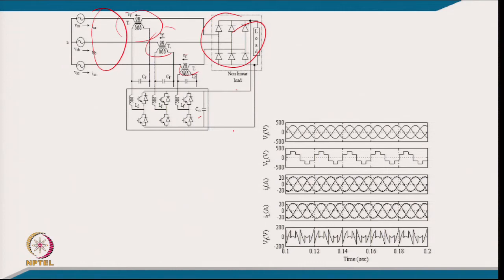So, in that case, after making the complete design and model of it with the data given in the problem, the waveforms are simulated and these are the simulated waveforms. The 3-phase supply voltage is balanced sinusoidal, and because of the conduction of all 3 phases, the per phase voltage is reflected at the input of the diode rectifier. If we inject the difference of these two, that is the series active filter voltage, in series with the line, then we will get the supply current balanced sinusoidal in phase with the voltage, and the same will be the current flowing at the input of the diode rectifier.